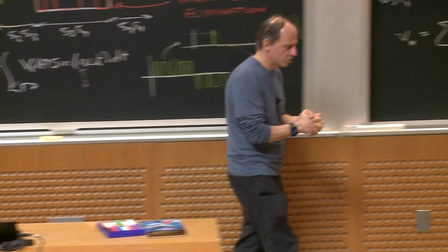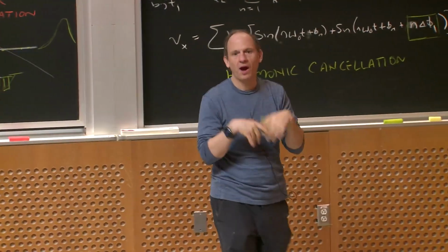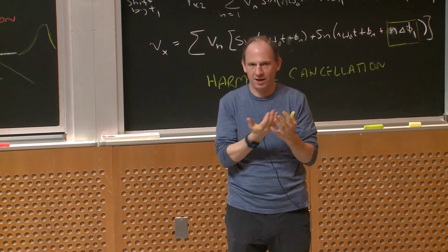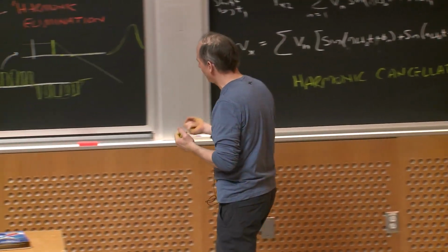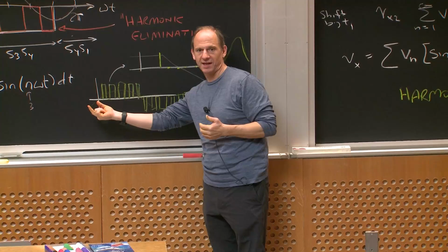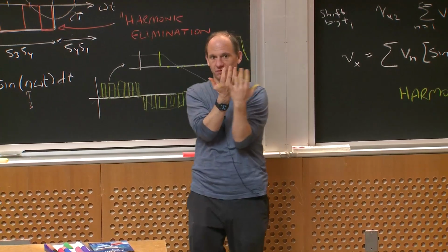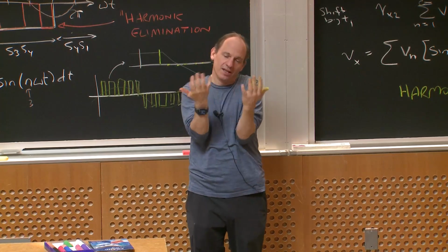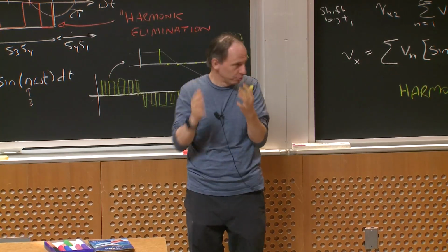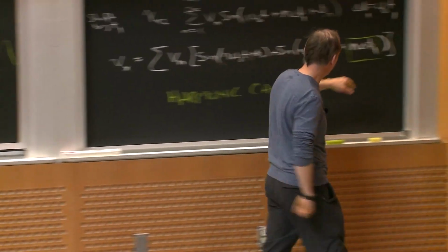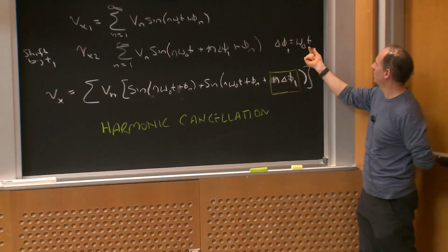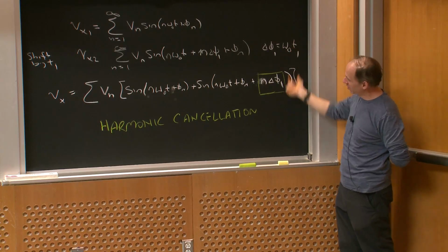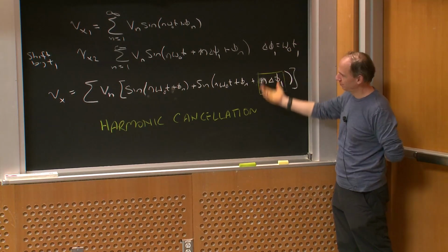Yeah, I wouldn't worry so much about the wires heating up, but your broader point is a good one. I'm kind of limited by timing angles with this guy, how much I phase shifted. If I don't control that very well, if there's delays between the circuits, depending upon how much absolute time that is, this harmonic is limited by how accurately I control that T1, right? So I want to be very good about shifting this the right amount.